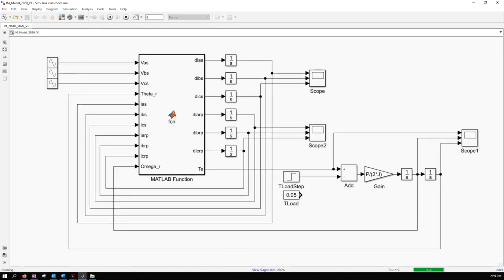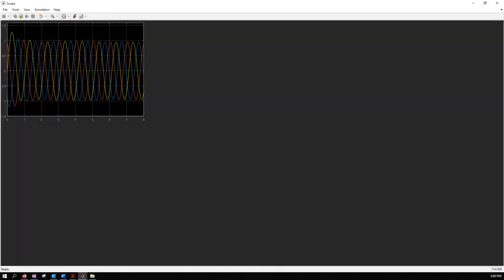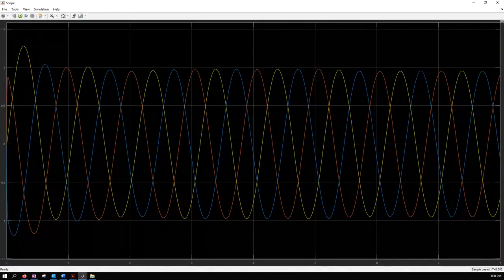Okay, yeah, it ran pretty quickly. So let's look at the currents. Maybe I'm applying open loop voltages here, and you can see this, right? So remember, we talked about at startup you're going to see a spike. Sometimes, depending on the machine size, this tends to be very large. But here it's not that big, and then you can see since the voltages and the frequencies are maintained at a fixed value, the currents are relatively staying at the same value.